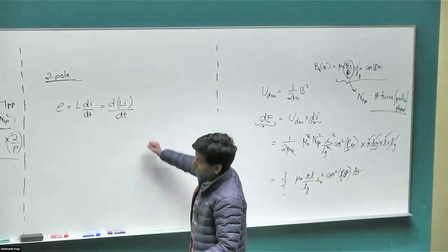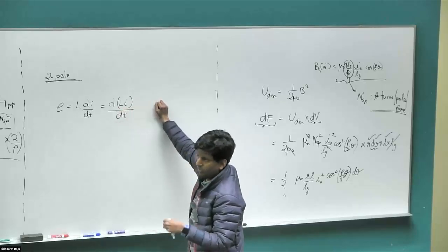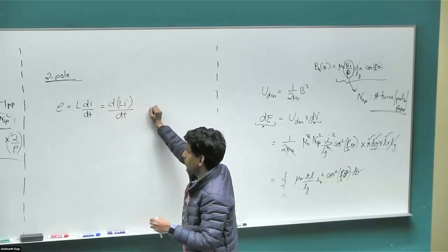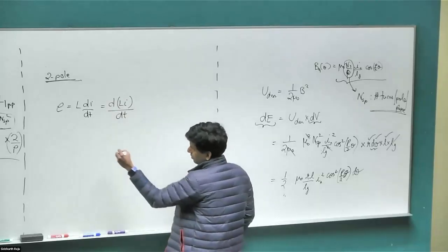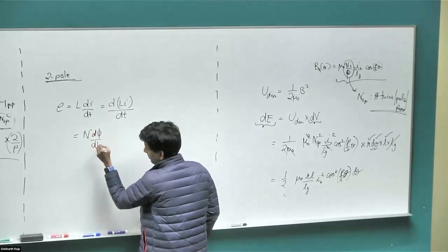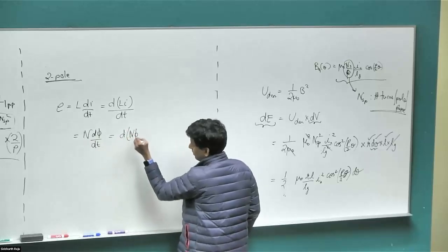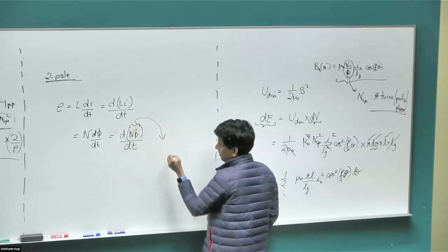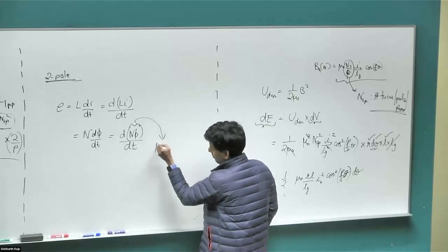And we said that when we go to a permanent magnet synchronous motor, the L still doesn't vary. But once we go to an induction motor, the L starts to vary. That way, we can't take the L out in case of an induction motor. But at least in a permanent magnet synchronous motor, it's absolutely fine to take the L out, right? So this is also equal to, from Faraday's law, n d phi by dt. And we are going to take this n term inside. That in itself is not varying, so you can take it inside. And here we are going to introduce a new term. In the textbook, this term has already been introduced in chapter 2 or chapter 3, but I wanted to hold off for a while.